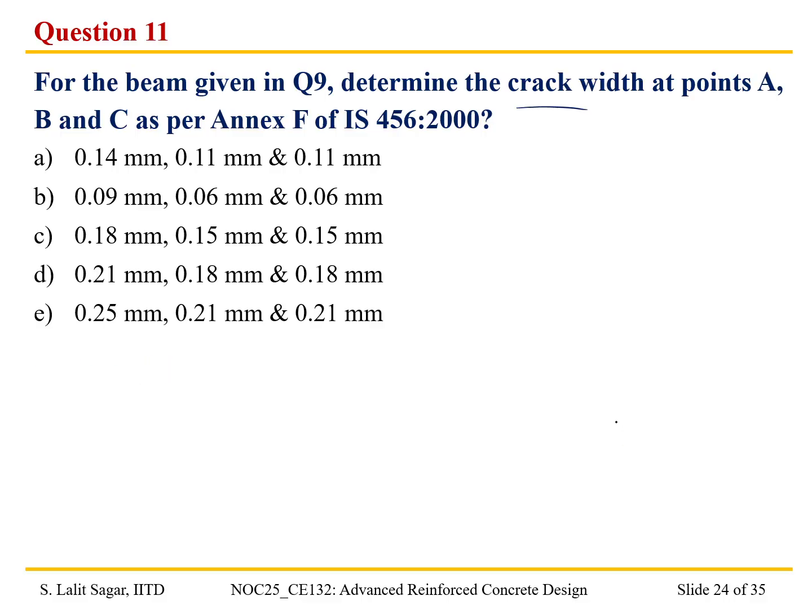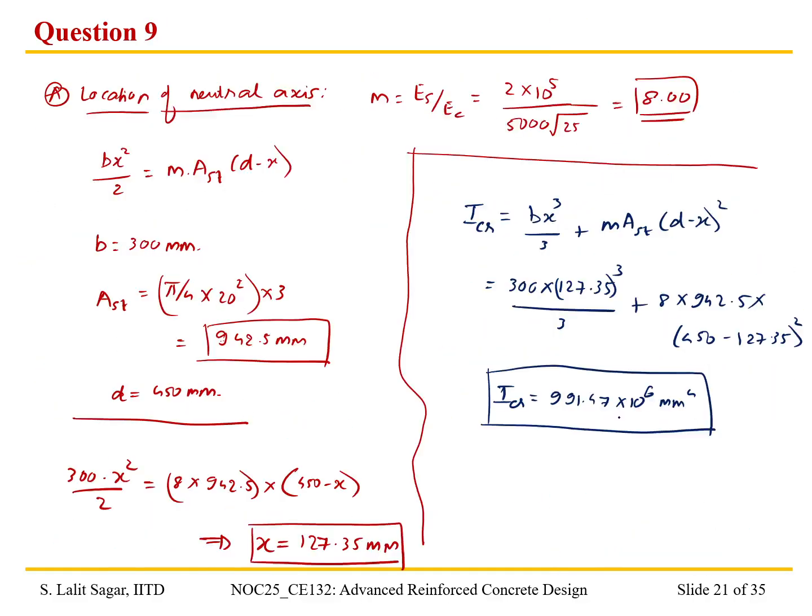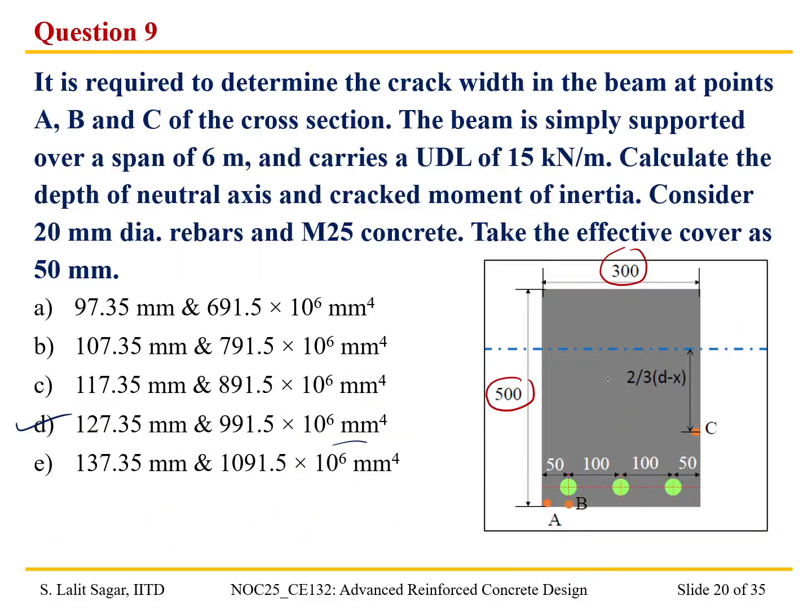Now why is Cmin 40 millimeter? Because if we consider this section, the effective depth is 50 mm, so you subtract this 10 millimeter, 50 minus 10, that is the minimum cover, or the clear cover, that is 40 millimeter.